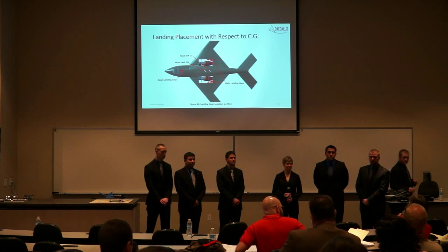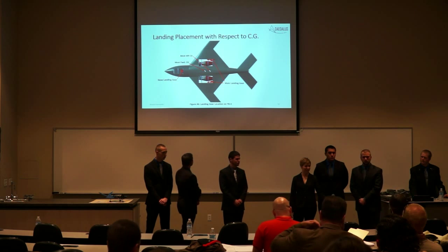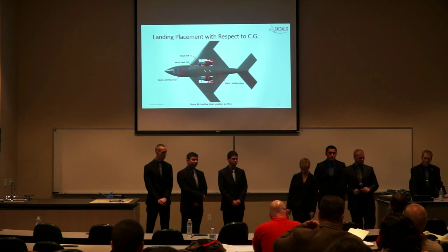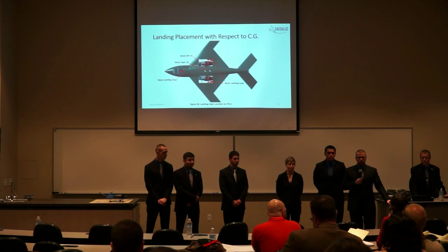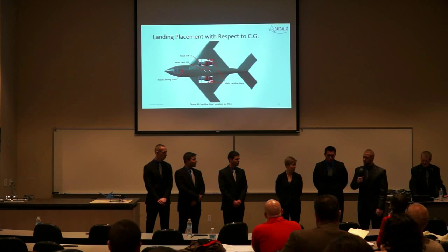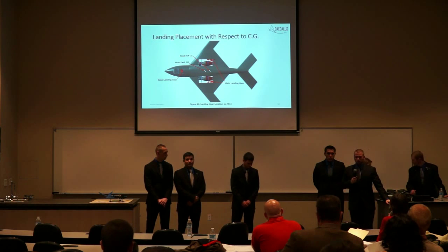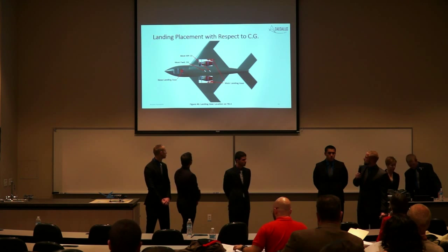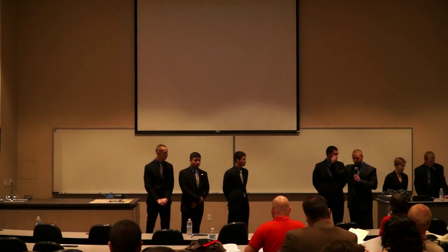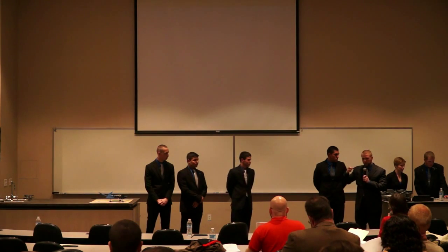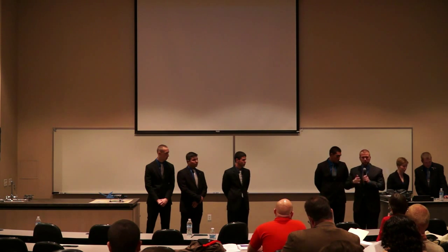Yeah, one more question about the thrust vectoring. During the thrust reversal, it only goes out the bottom? Yes. Okay, so how's that going to happen? A lot of the CFM56 series have built-in thrust reversal capabilities. So what we would end up modeling is designing ducting that would lead from the nozzle portion and down through the landing gear door bay.